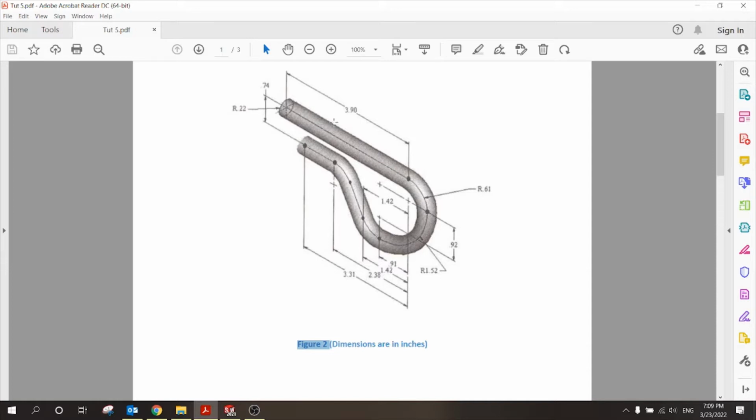From this point to this point, I can do a normal extrude. But it's not easy to create a half circle, this tube, and then do those curves in 3D features. So instead of using the command extrude, I can use the sweep command, and I would say sweep this circle through this specific path.